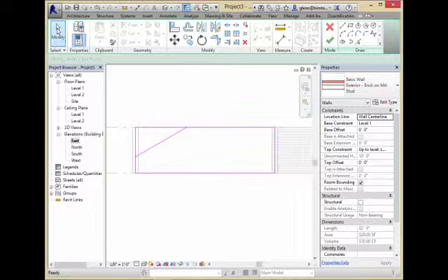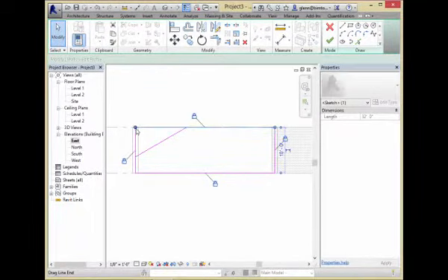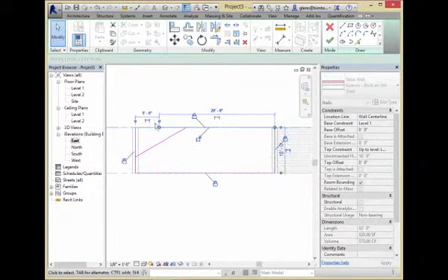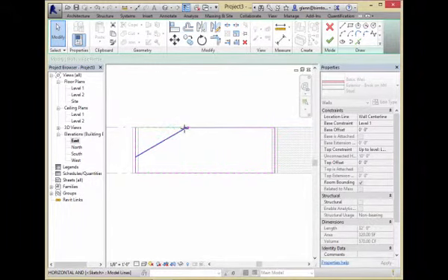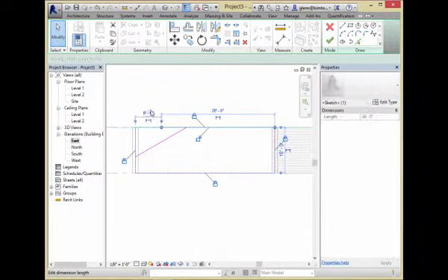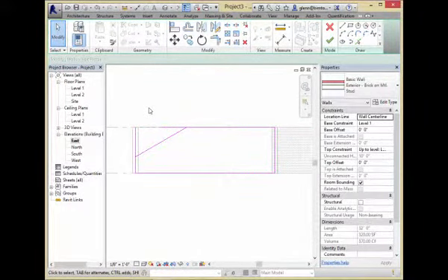And how we get rid of that, we've got a couple of different options. We can choose a line and drag that back. And if I get real good, I can actually pull that all the way back to here, and it'll snap, hopefully, really nicely. But what I want to show you is a better way to get rid of things because it has a little more precision to it. Dragging and getting it to land just right, if you're lucky, it works that way. But a much better way that you'll learn to start using is something called the trim tool, which is right here in the Modify tab.